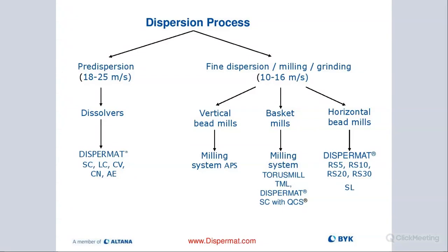Is there an upper temperature limit during milling? That depends really on the material. We like to stay, ideally, I mean, that's how I set up our mill, about 50 C, 60 C, anywhere in between those two is where I want to be when I'm milling. Anything more than that, I'm already worried with solvents, especially, depending on the flash point of the material. We always need to look at that. That might actually be lower, but cooling is very important. But usually I try to be within 50 to 60 C.